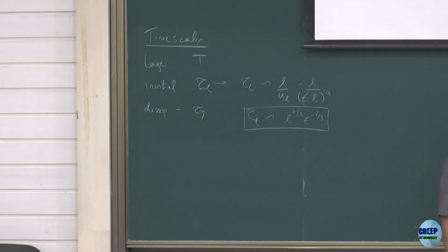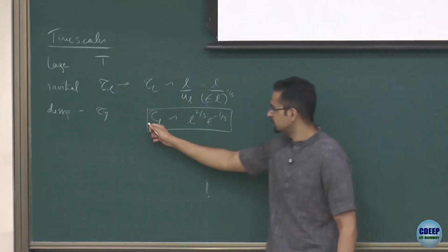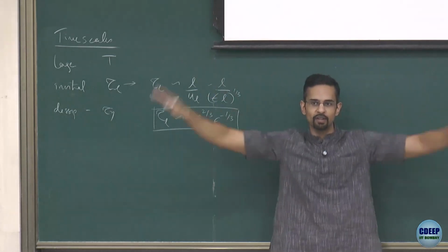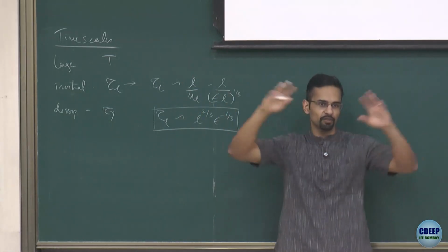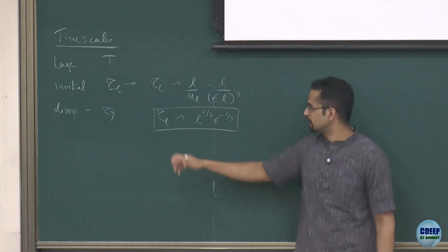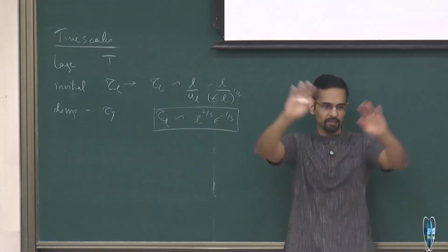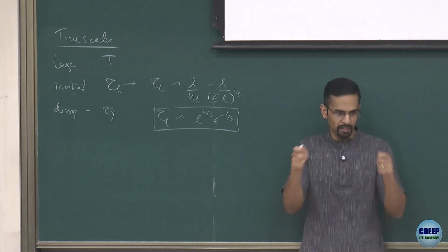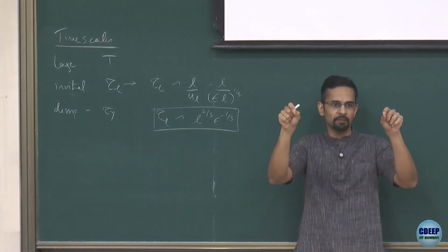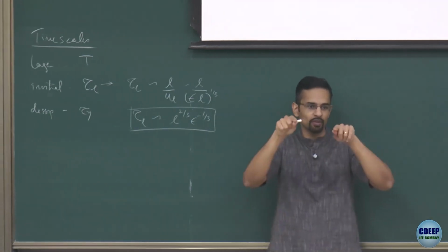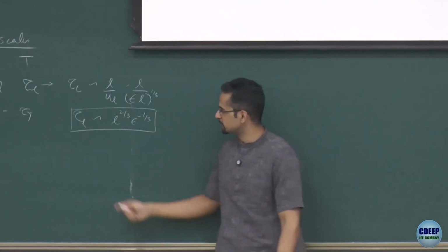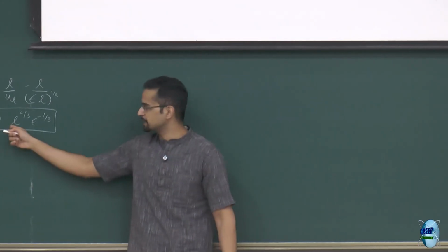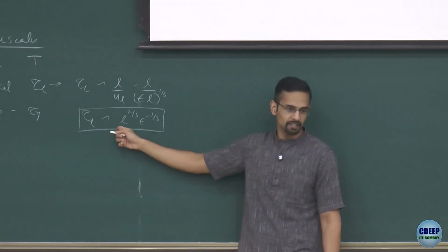Okay, so what this tells me now is, one way to think about it as a cartoon is you have different scales, different eddies, some kind of gyrating motion. The larger ones have some time scale, the smaller ones spin faster. They spin faster, that means tau should be smaller. That means the time it takes, if you watch a particle in that particular eddy, to go around, is called a turnover time. So this eddy turnover time, or the typical time scale of processes on that scale, gets smaller and smaller as L decreases. But not linearly.